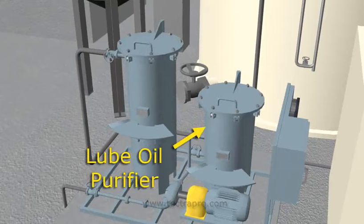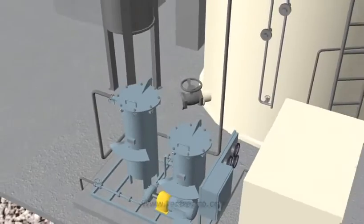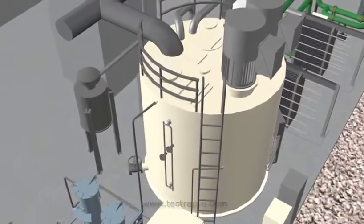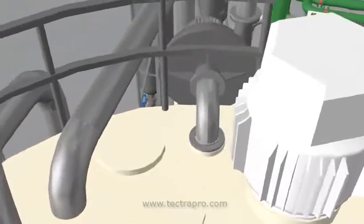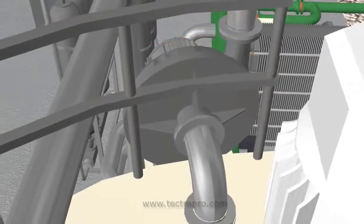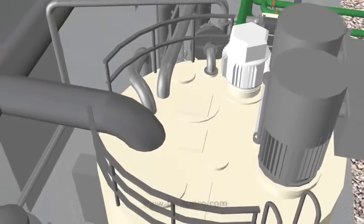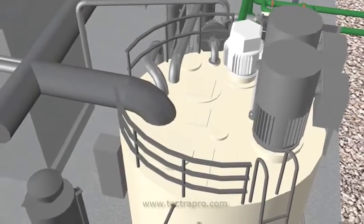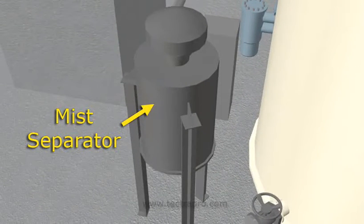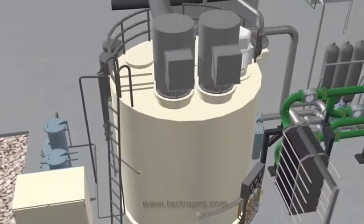The oil purifier takes oil directly from the main oil tank and pumps it through extremely fine filters. The filtered oil is then returned to the tank. The main oil tank has a turbo blower type vapor extractor to maintain a negative pressure on the oil tank. Such a negative pressure aids in oil return flow to the tank and also helps reduce external leakage from the oil system. The vapor extractor blows directly into the mist separator. As the mist is removed, the collected oil is returned to the main oil tank.